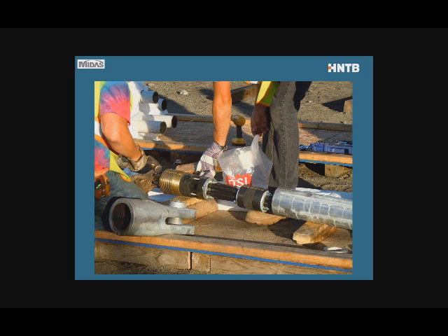So in the middle of the picture, where the 2 workmen are active, you see him with the hammer. He's just seating the wedges at the end. You can see the anchor plate with threads, and then these 2 assemblies. They're there to seal the system against moisture intrusion and to hold the pipe in place.